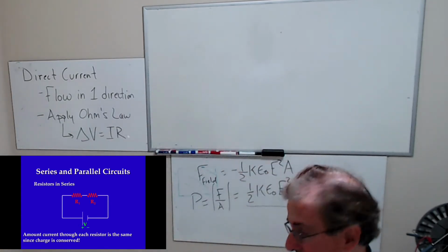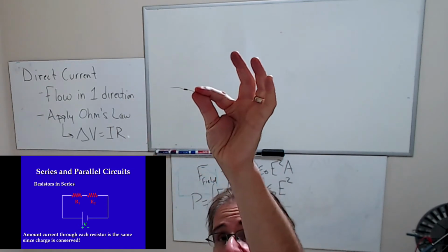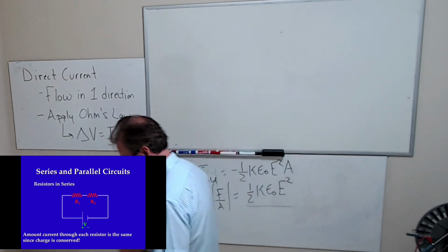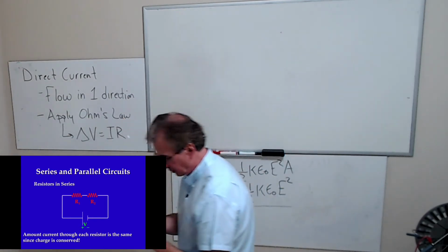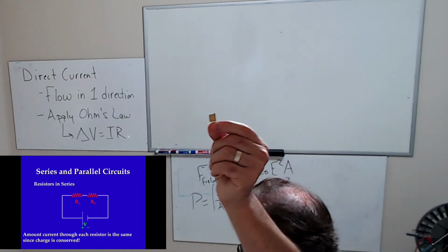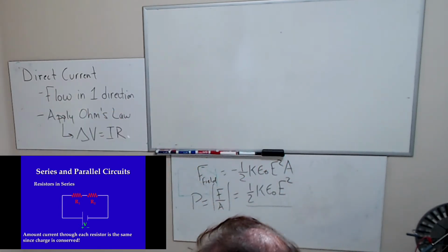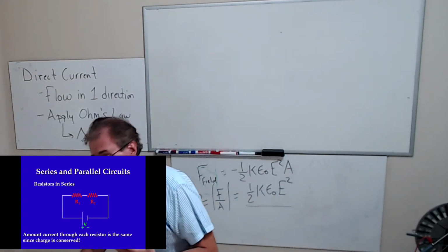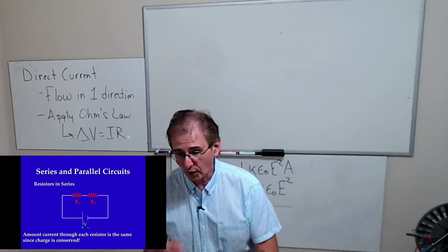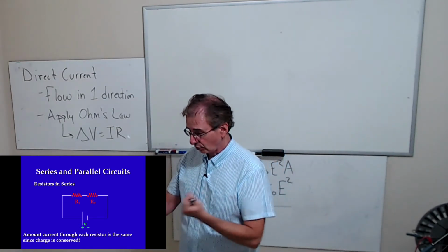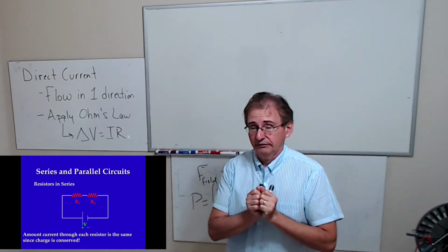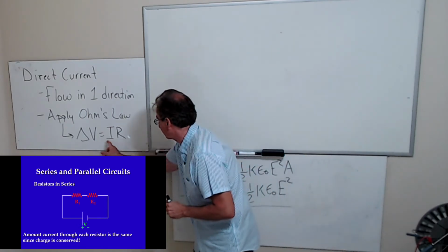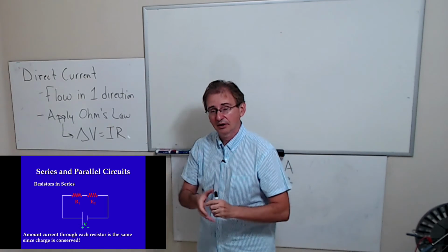They can be this small. This is a very small resistor. You're going to be using this resistor in your next lab. This is another type of resistor. Again, it's small. And that one's a variable resistor, and I'll talk about that in the lab today too. So there are different kinds of resistors. They could be wire wound. They can be made out of carbon, and those resistors are generally devices that do obey Ohm's law, meaning that delta V over I is a constant over a range of applied voltages.